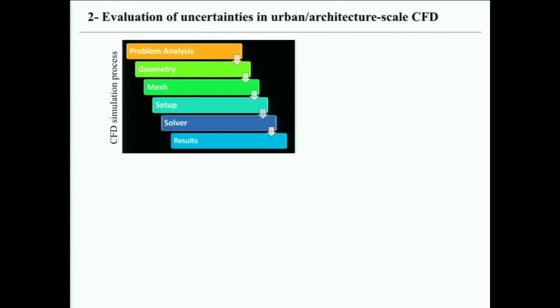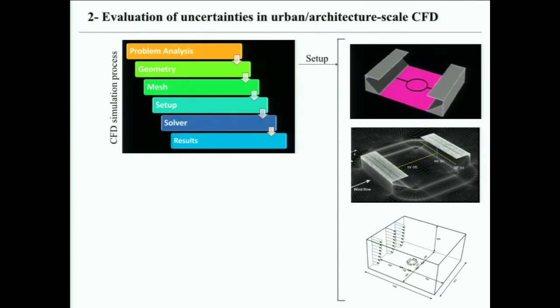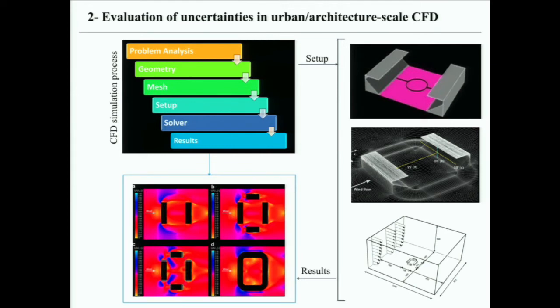So as I mentioned earlier, just a quick, simple way to understand what CFD is. Today we talk about CFD, but I'm 100% sure some people probably don't know what CFD really is. So the process of CFD is that we design a geometry. If you're using commercial software or codes, maybe you can use Python for coding the geometry. Then we assign the mesh, which means the sensors. These are the sensors with which we can understand and analyze the different variables. And then we set up the boundary conditions. We try to recreate the meteorological weather conditions. And then we run our codes, our turbulence model, for example. And once we get the results, we can understand and optimize according to our needs.